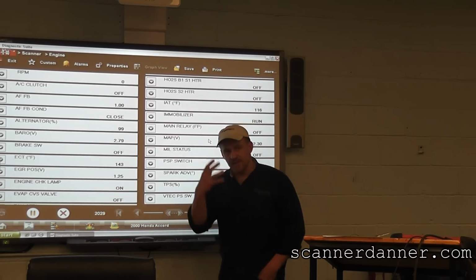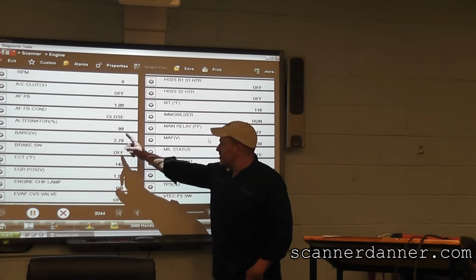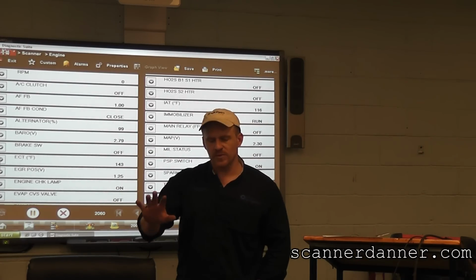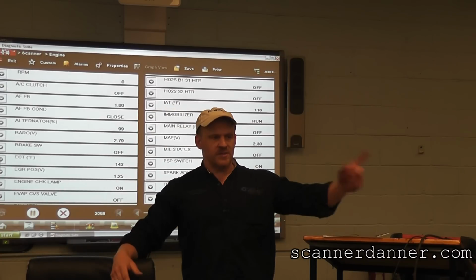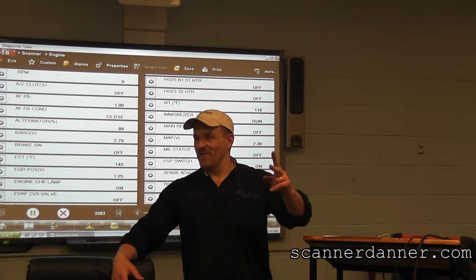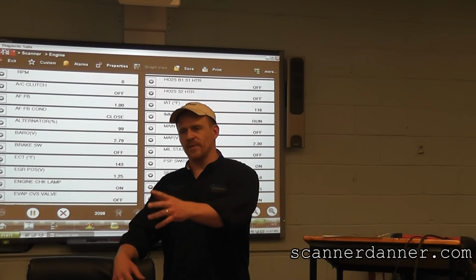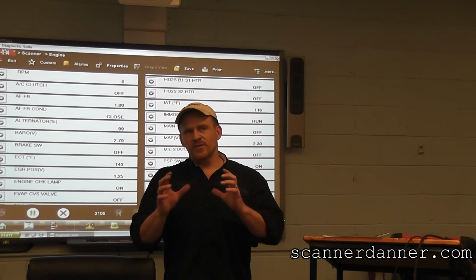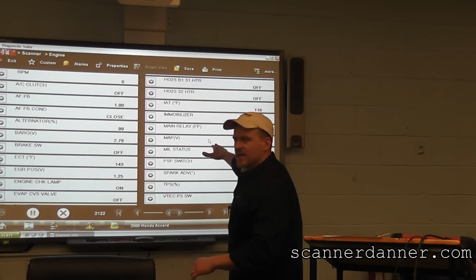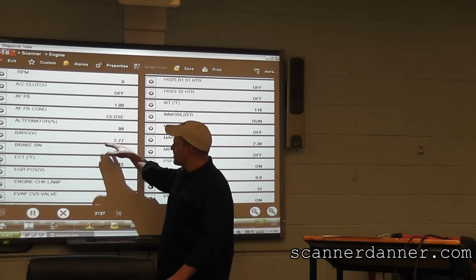I have a conflict in my mind, and that conflict is why is my baro not reading 2.3 volts like my MAP is, because it should be if that's the case. There's two options. One, it has a separate baro sensor. Two, I don't know, is the other option. So what I'm addressing to Rob in that question is, here's something I know for sure, and that's my MAP sensor's messed up. Here's something I don't know for sure yet about this baro reading.